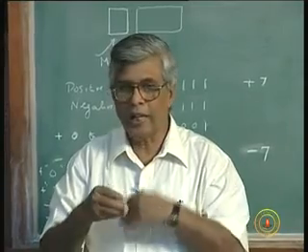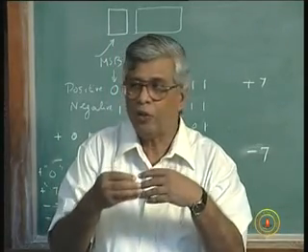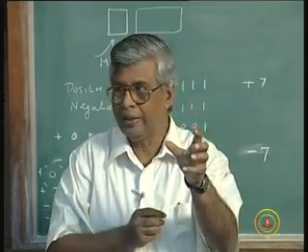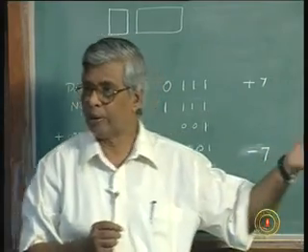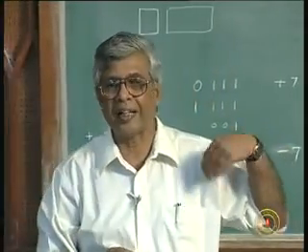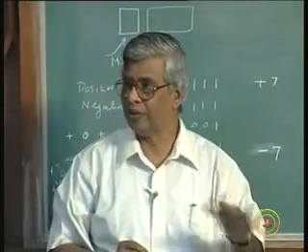So all the arithmetic operations should also result, the sum or the difference should always be less than 3 bits in magnitude. Only then, with this 4-bit number in 2's complement representation, I can carry out additions and subtractions whose result does not exceed 3 bits, whether it is positive or negative.